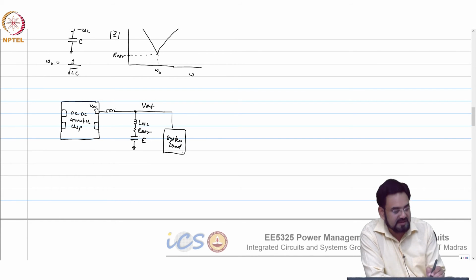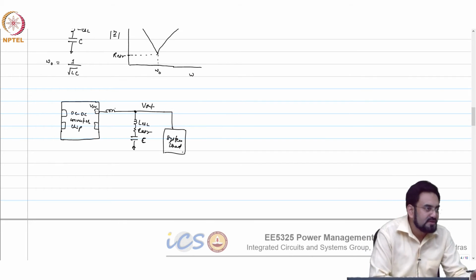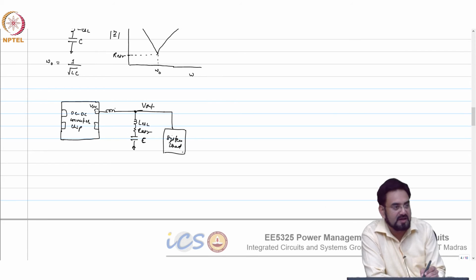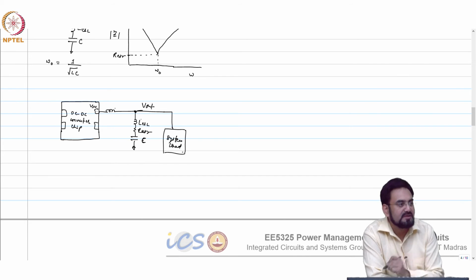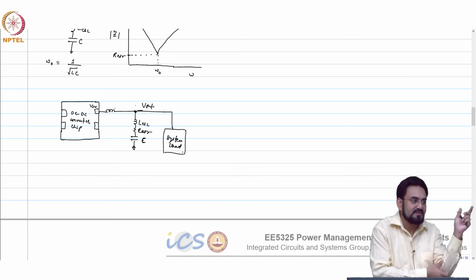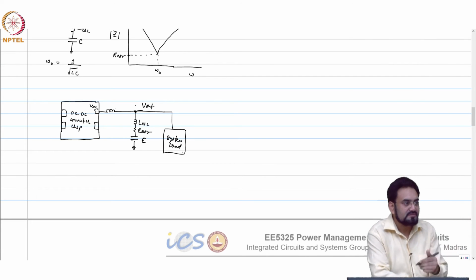So when you are connecting the cap, you have to make sure this capacitor is closer to your system. Okay. So that's the one thing, you want to avoid the R also. Wherever V out you are connecting, it will be placed close to this trace actually. So it will look more like a star connection.